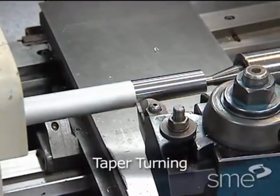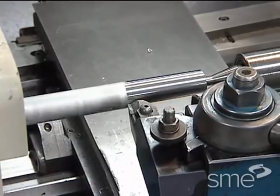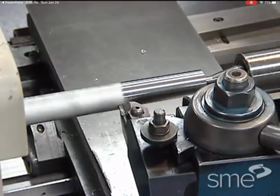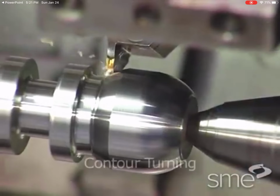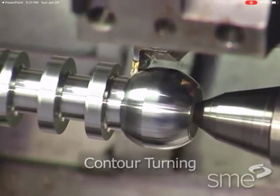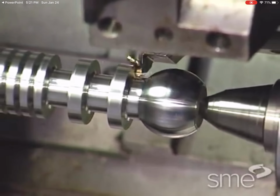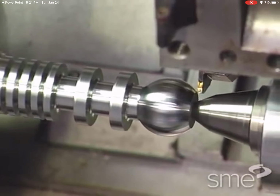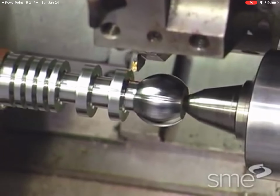Taper turning produces a taper along the axis of the workpiece. Tapers are produced by offsetting the tailstock from the center line or by using a taper attachment. Short, steep tapers can be turned using a compound rest. Contour turning, or profiling, was formerly performed by having the single-point cutting tool trace a template of the desired profile shape. This has largely been replaced by CNC turning, in which the desired contour is simply programmed into the machine, which directs a cutting tool to cut the contour.